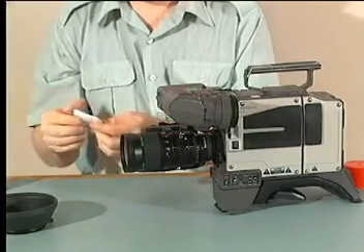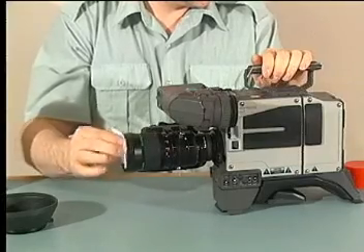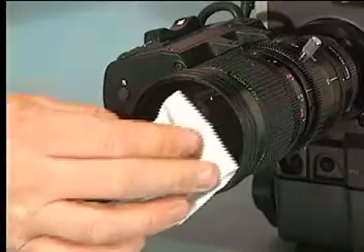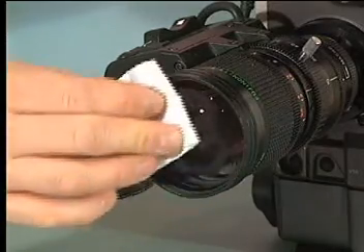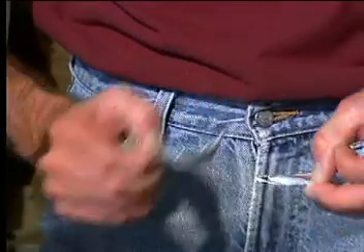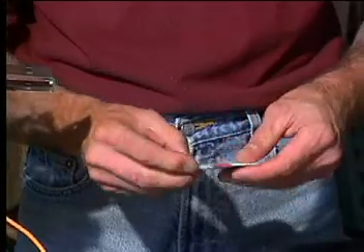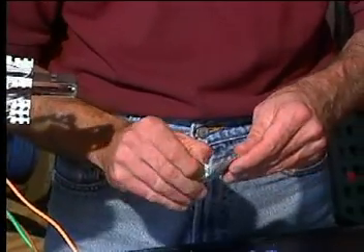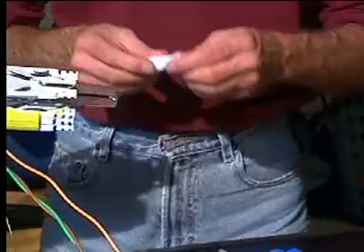Single-mode connectors have precision optical surfaces that are more critical than the lenses of the finest camera equipment. This is why you will never see a professional photographer cleaning his lenses with any alcohol products. The reason is that alcohol is hygroscopic. It attracts moisture from the air. In many environments, serious contamination can be accumulated on the pad within seconds after removing it from its packaging.